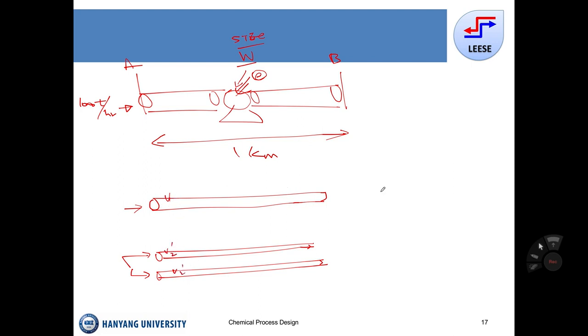So you have a different pressure drop. Okay, so pressure drop is different. Then are you going to use one single pump? Are you going to use two pumps? Based on that, you have different size and different pumping requirement. So it's not just a simple calculation from the viewpoint of the pump; that is connected with the design of the pipe.